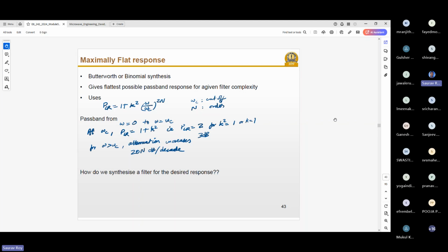So now how to do that? For that, in the Pozar book or any other filter book, they will give you a chart or a table. In some cases in the book, I found a plot for different orders, up to at least 20 different orders, showing the roll off. So you have to select which roll off is suitable for your design. Accordingly, you first select the order of filter.